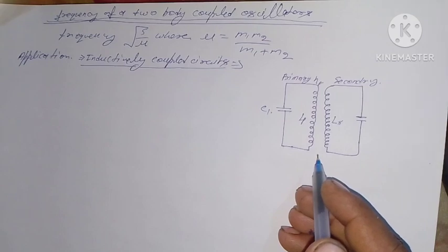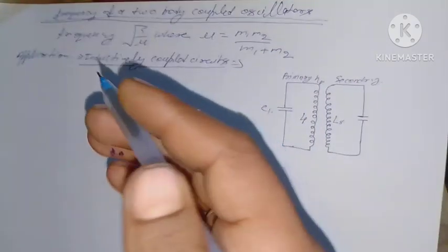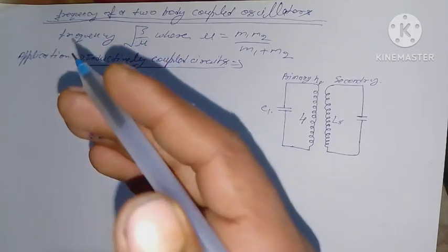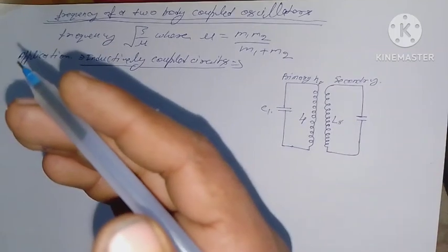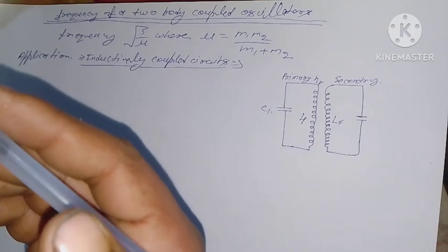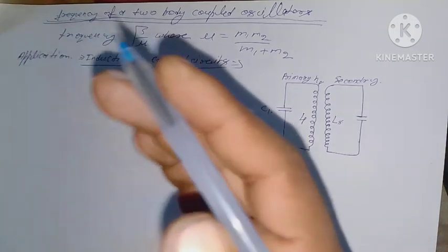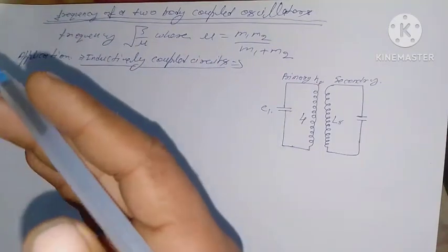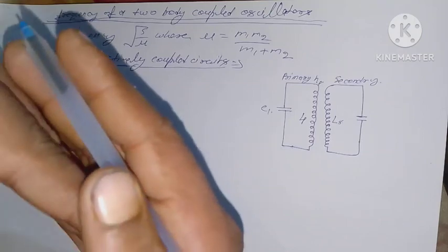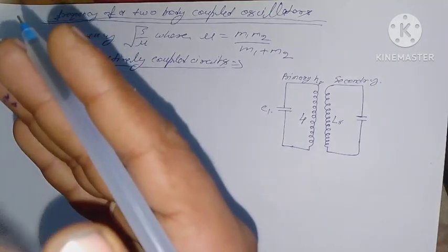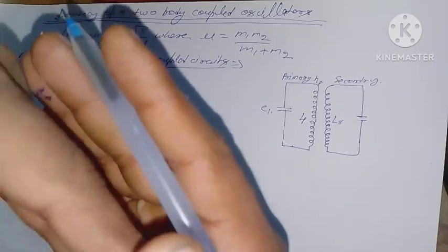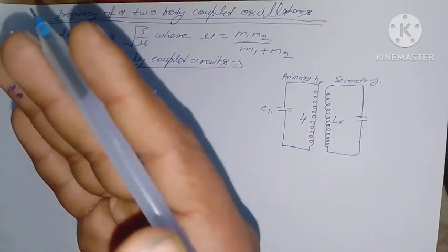According to Faraday's law of electromagnetic induction, whenever the magnetic flux in one circuit changes, an induced EMF is set up in the other, which is proportional to the time rate of change of magnetic flux, and lasts only for the time the change is taking place. The most familiar example is that of a transformer whose working depends on the mutual induction between its primary and secondary coils.